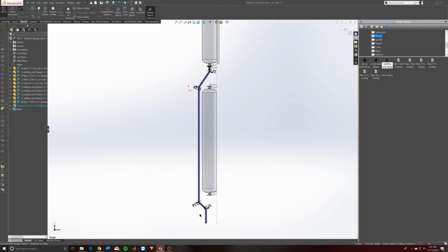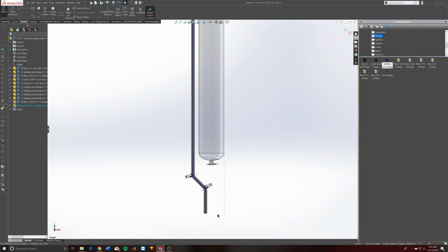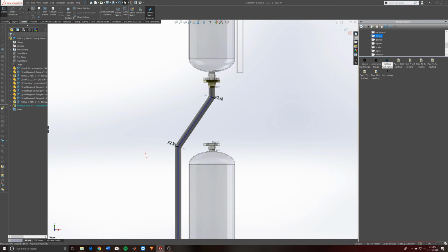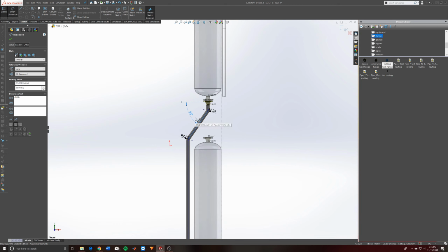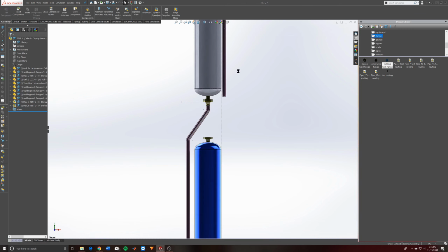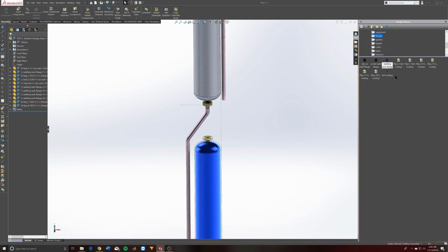I'm just going to end the pipe here, but this is where it'll go into the injector of the engine, and we'll have the second pipe going right here. With the Jet A and the liquid oxygen, I'd be a lot more careful with angles, especially with liquid oxygen, but this is showing a 35-degree curve. Essentially, it's off this axis, so you shouldn't run into any issues. Usually issues come around 45 degrees. So we're going to leave that guy and do this one.